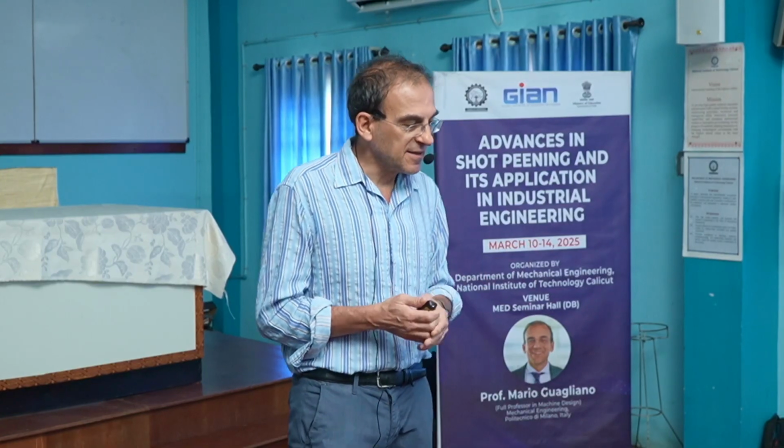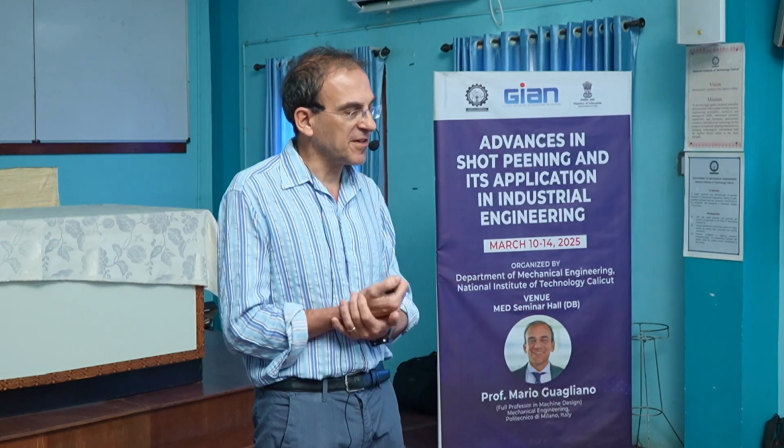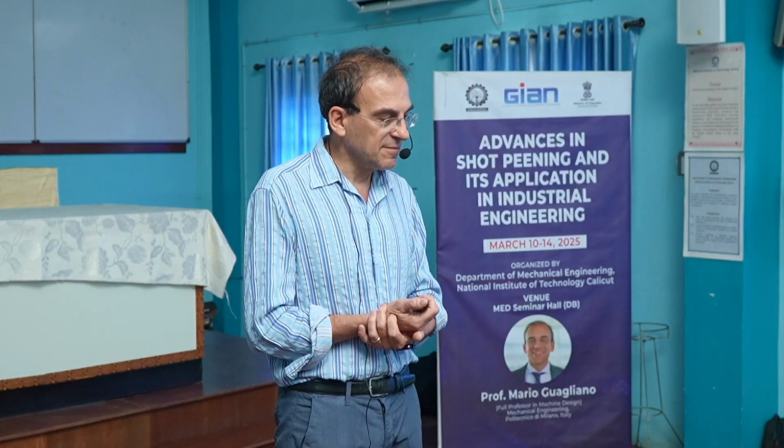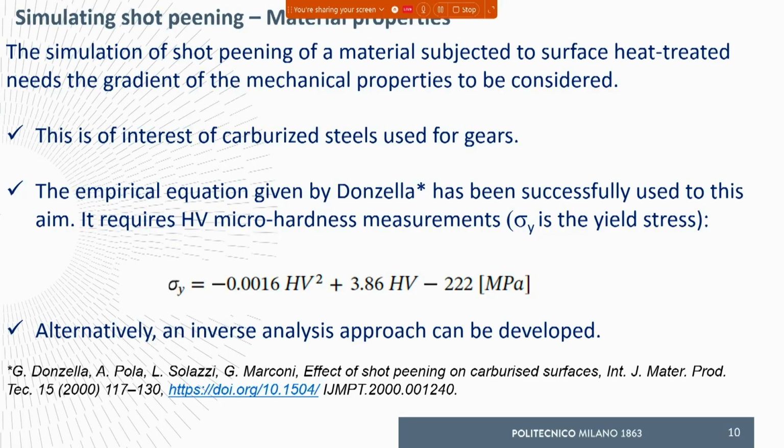Indeed, we had this problem in a cooperation we have with Rolls-Royce Deutschland, Rolls-Royce Germany, and finally we used an equation that is this one, where the yield stress of the material is found to be related to the Vickers hardness by means of this equation. That is an empirical equation.